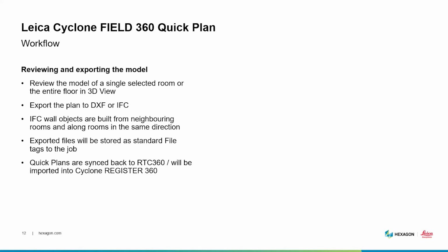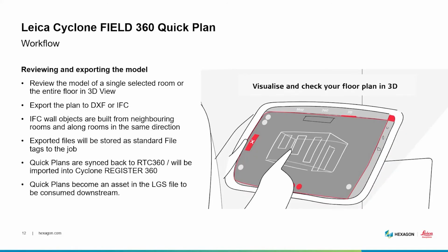Once you're finished with all your rooms, you can visualize your 3D model in the 3D viewer, so you can actually see the entire geometry you've collected, and you can overlay that with the point cloud, so you can see both the created geometry and the point cloud. You can also do this for a single selected room, or you can select all the rooms at once.